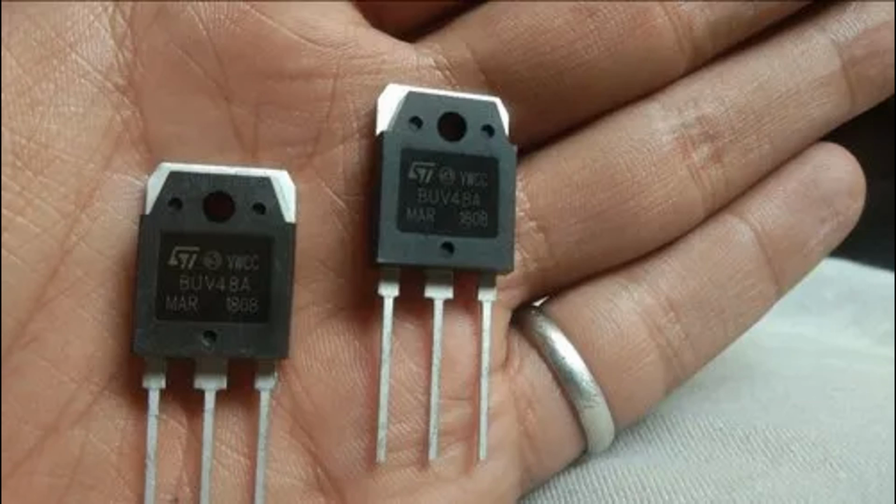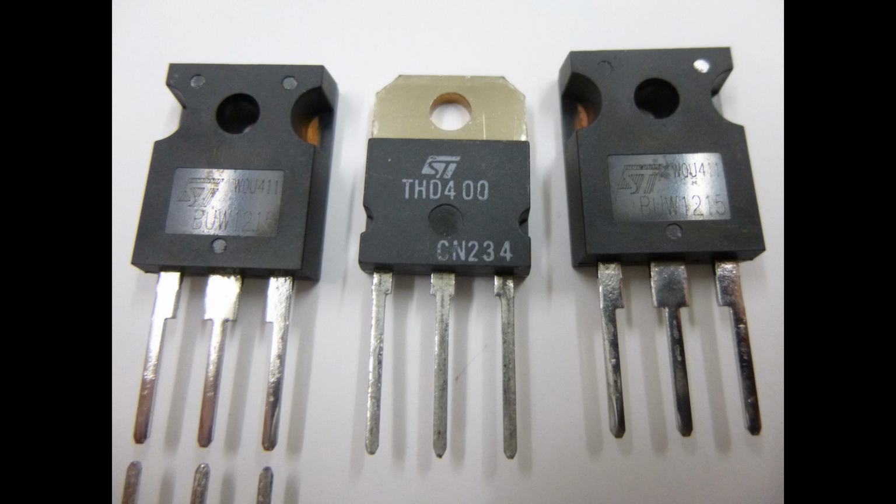Transistor action: the transistor, based on its configuration, common emitter, common collector, common base, etc., amplifies the input signal. The transistor operates in its active region, where small variations in the input signal result in much larger variations in the output signal. Signal output: the amplified signal is obtained at the transistor's output terminal, collector for bipolar junction transistors or drain for field effect transistors. This output signal is a larger, scaled-up version of the input signal.